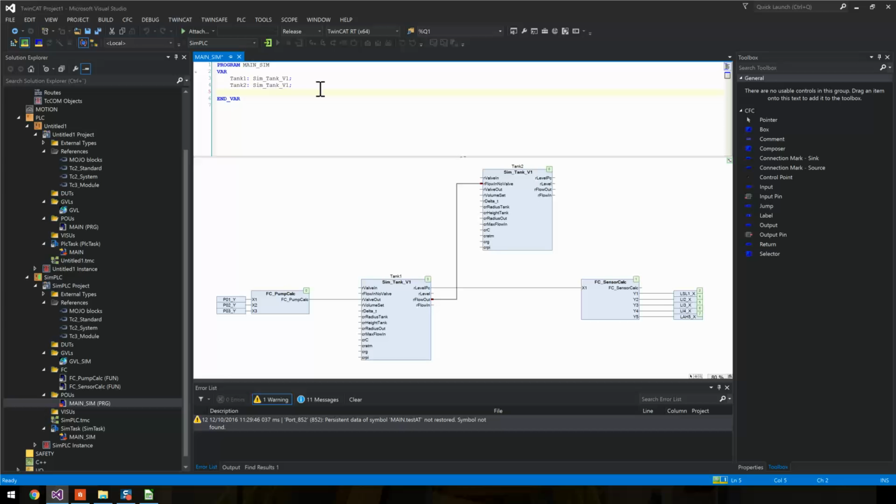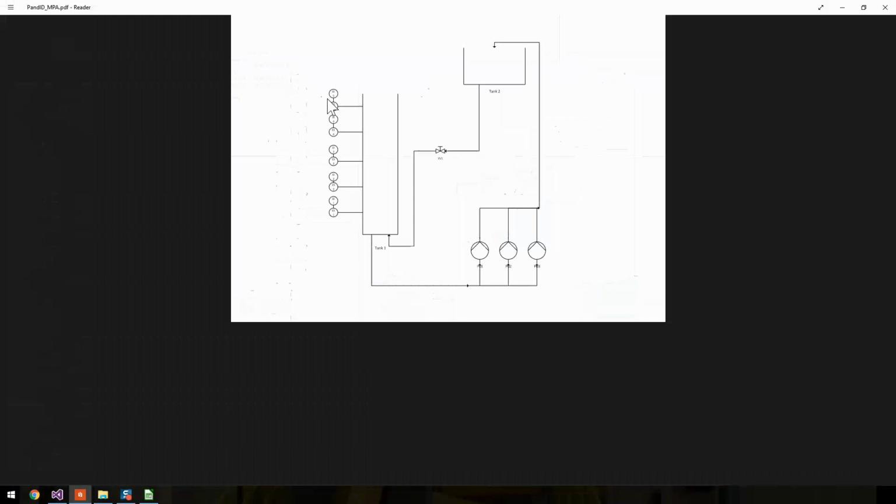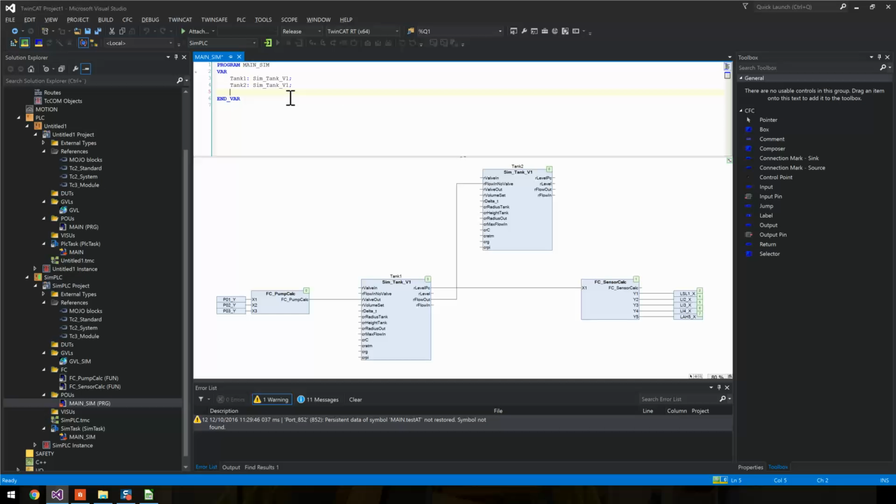So let's add a variable for the manual valve xv1, unspecified valve 1. Make that a yield value and initialize it as 0.